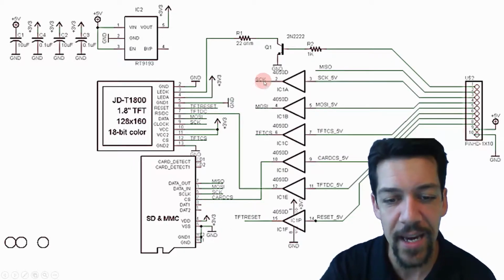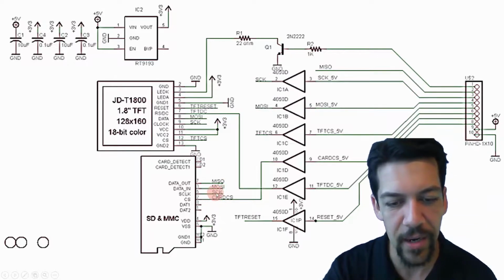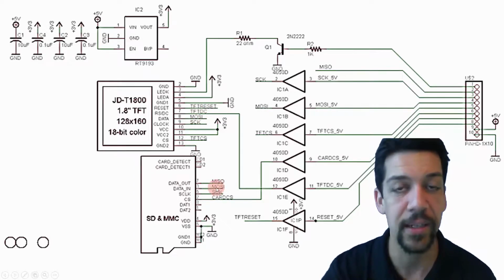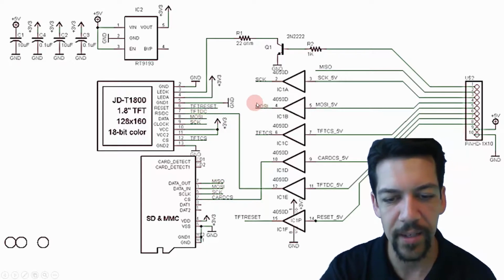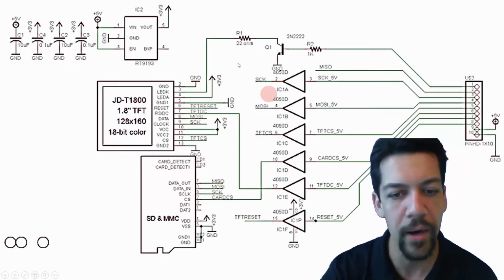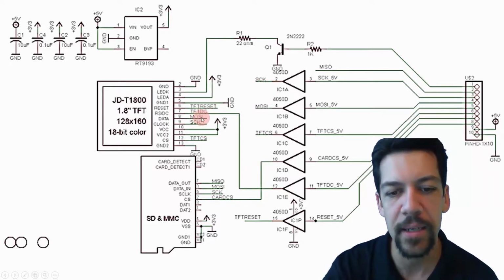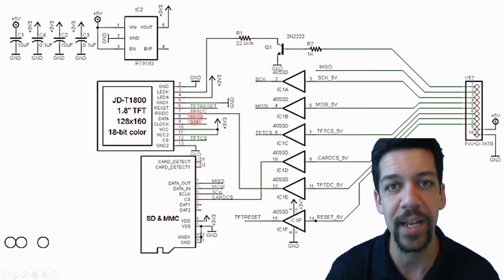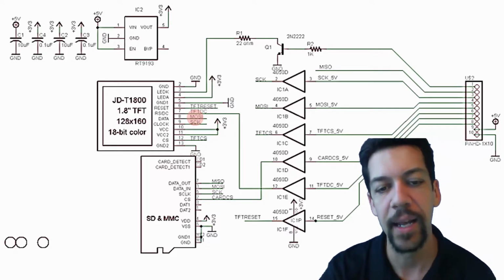So this SCK signal is actually connected to the SCK down here. And you'll notice there's a bunch of other signals that are defined here. Here's MOSI, that's connected in 3 places. It's connected here once, it's connected here once, and it's connected here once. If we had all of these wires running between here, it would be a big rat's nest and there'd be no clear way to follow it. So just by naming the signals and having them jump across between them, we're making it clearer without getting people confused about how they're connected together.